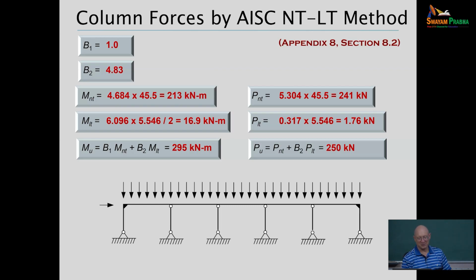And of course, this falls in the category where my understanding of the Indian code would basically say you'd better run a second order analysis, right? And the Eurocode would say, yeah, you've got to do some special considerations here on this frame. It's got a lot going on. Correct. The American approach would say, okay, we've done the stiffness reduction.